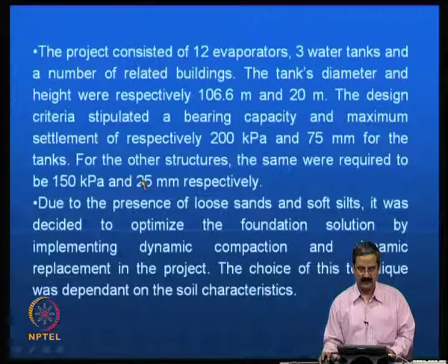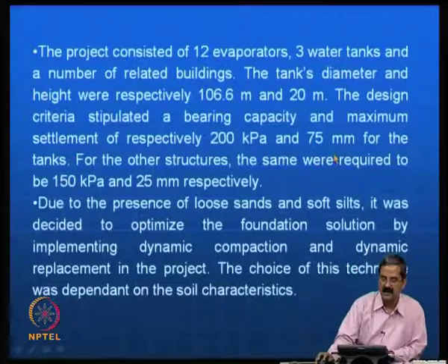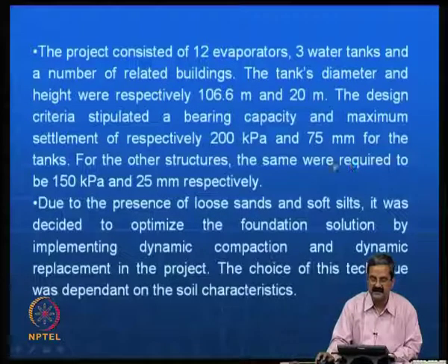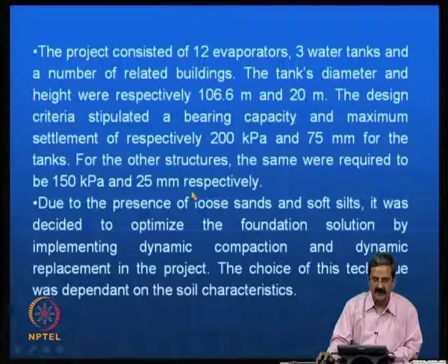You can see that for the water tanks they had 200 kPa as the bearing capacity and 75 mm as the settlement. For other structures the requirement was 150 kPa and 25 mm respectively. For the water tanks it could be a little higher, it may be a raft type of foundation, but for isolated footings you should have a settlement of 125 mm or something. So it is very important that the whole area needs to be stabilized.